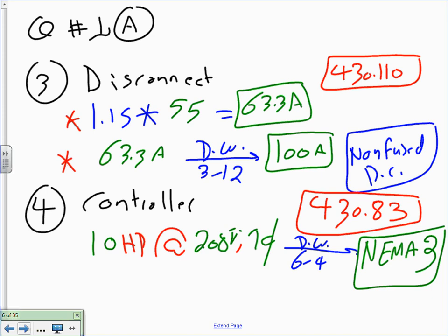And in the table, you can go to voltage 208. Remember, it's 208 voltage in this. And because there is no 208, which voltage did we go to? We went to 240, the next standard. Remember, it says also single phase. Write yourself a note when you use this table: 208, go to 240, single phase. That's where you go, because otherwise there are multiple of them. You need to know which voltage and what phase.